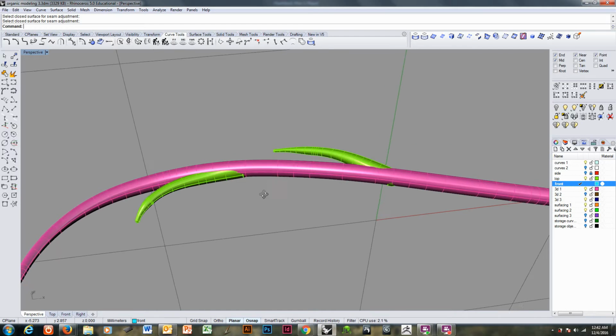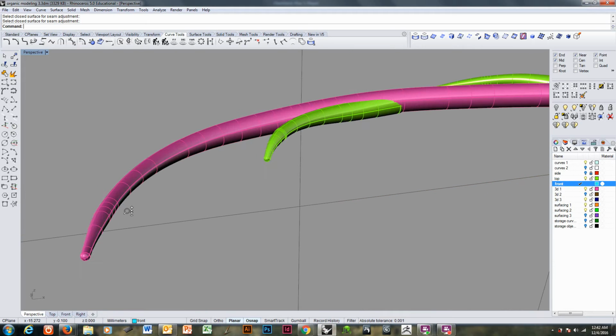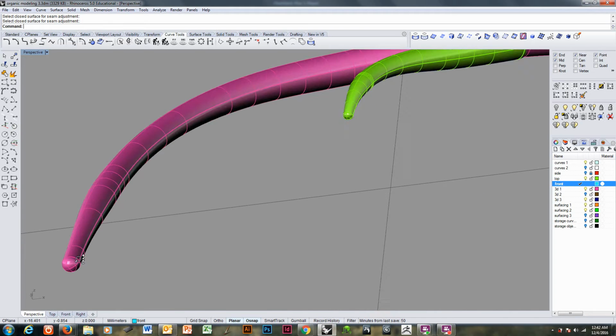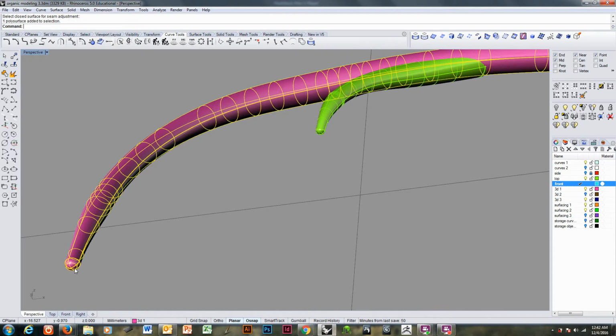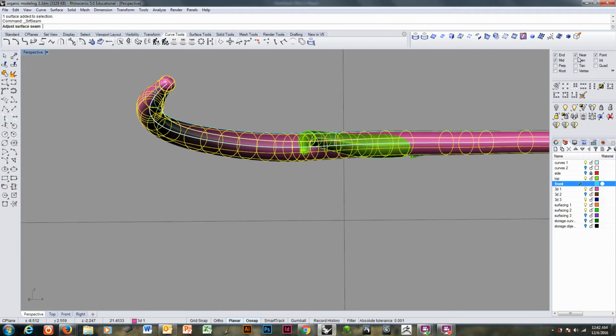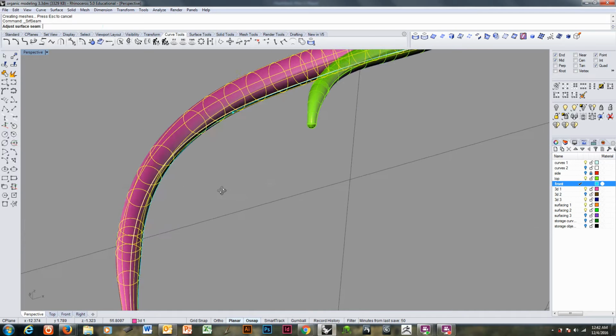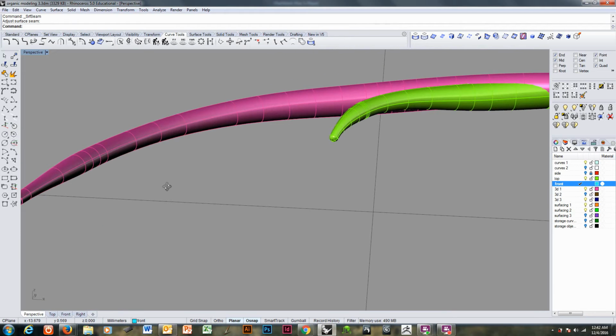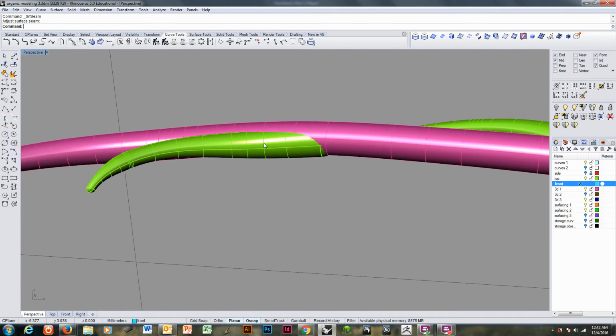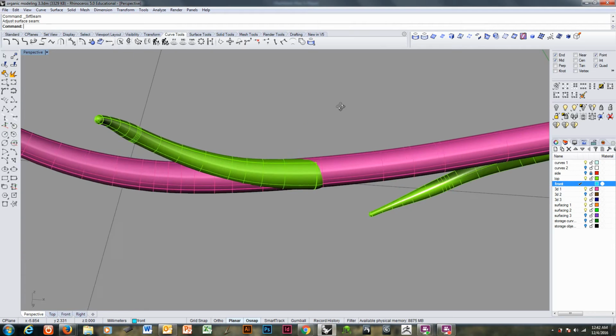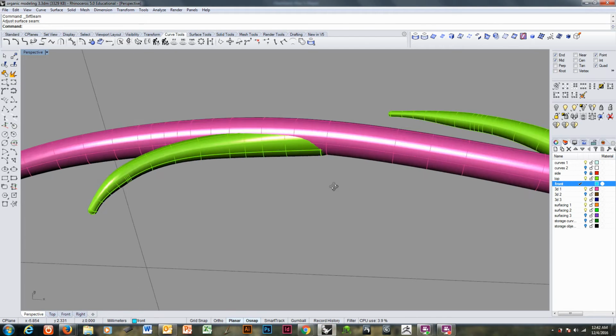Okay, it's a poly surface. Notice this weird little ball on the end, how strange that is, but okay. I'm going to explode this. It'll be 3 surfaces. I'm going to change the seam on this one to the bottom quadrant there, because I don't want a seam running right up the side of this. That'll be a little bit of a nightmare.